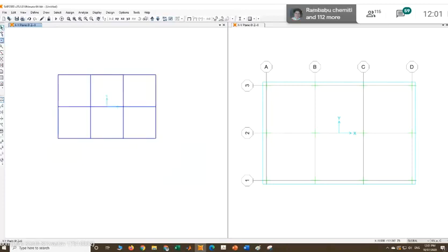From this panel, we can assign additional members like frames, additional joint, or additional slab, or any area section. This gives draw special joint, draw frame, draw quick frame. These three are for frames, and these three are for slab. So I'm using this for assigning a quick area.